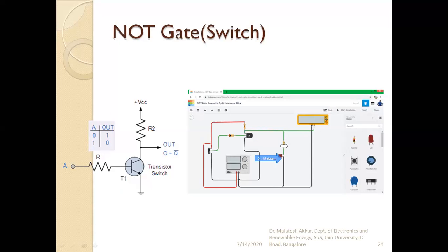So I have just connected the resistor here in series with the LED. Okay, so the intensity of this LED depends on the current flowing through this. The current through this resistor is what? It depends on this resistance value. This is an extra part compared to the left circuit. Okay, so only this resistor, this transistor, and this resistor R2 or RC, we can say. This is RB or R. So only these three will form the circuit, including this power supply.